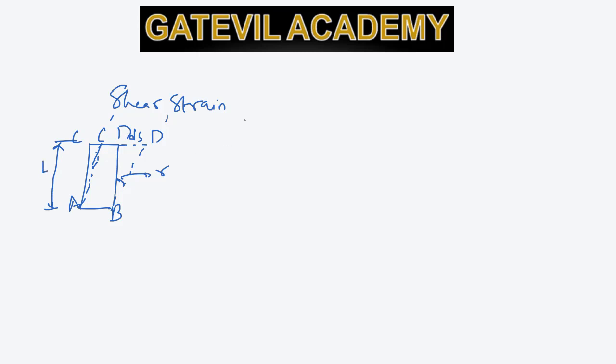So shear strain is nothing but ds by L. This is the distortion produced. So this will be equal to tan of gamma. In civil engineering, we see a very small distortion, not a very huge distortion. If this distortion is small, this tan gamma can be represented by just gamma.